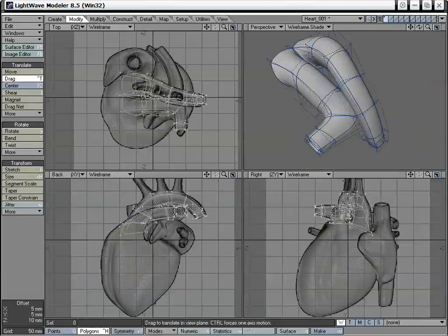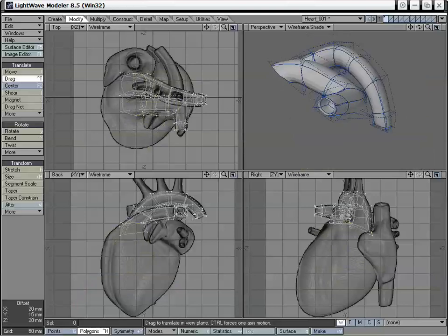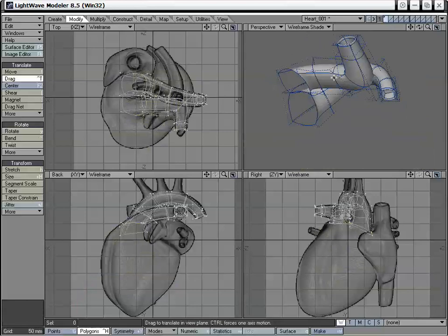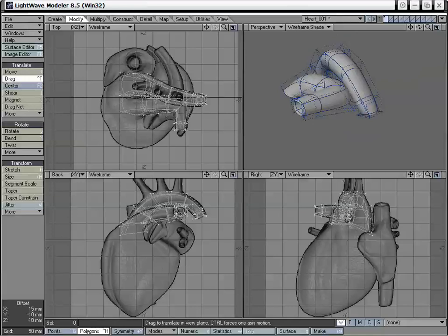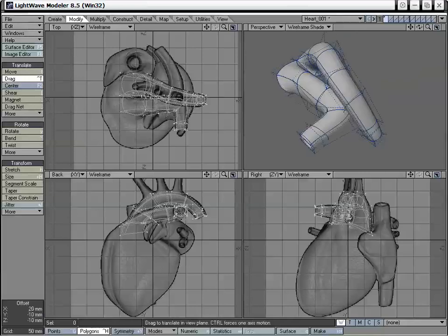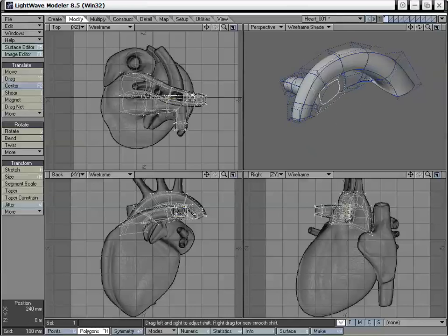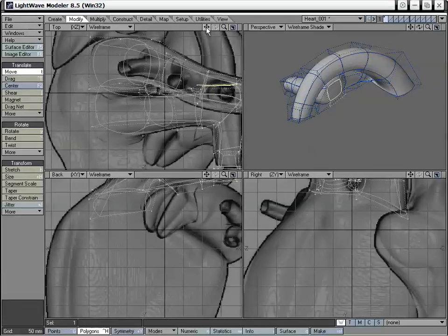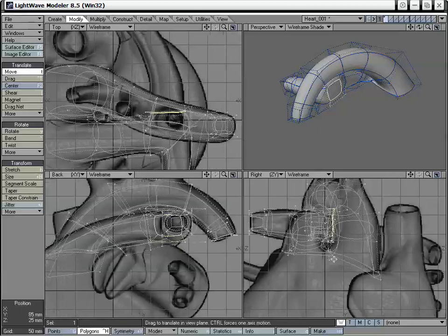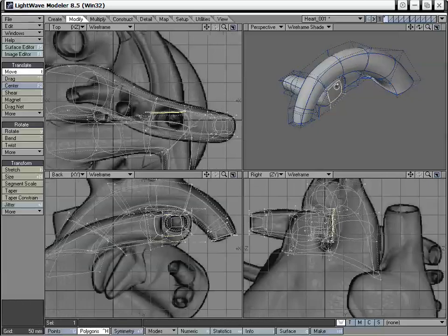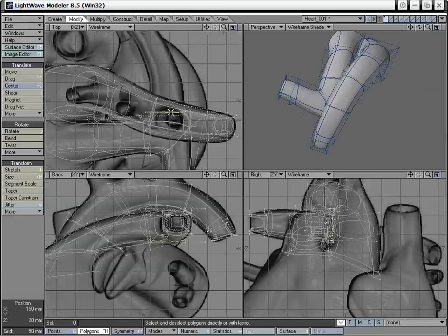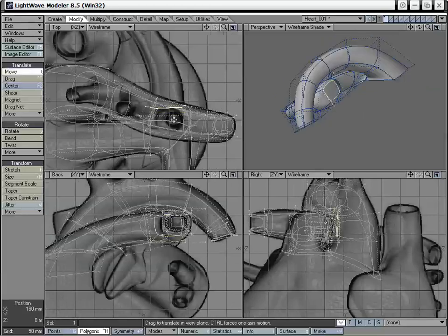So I'm going to hide that bottom part now, which once again is the minus key. And Shift T, I'm just going to do a little bit of editing on this top part right here, just to make it a little rounder. Maybe bring it in just a tiny bit. Okay, so we'll grab that polygon now, and Shift F, right mouse click, and now we can start extruding from there. Just zoom in a bit. And T to move. Oops. Deselected it by accident. And just move that into place.